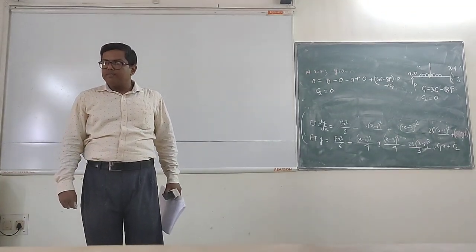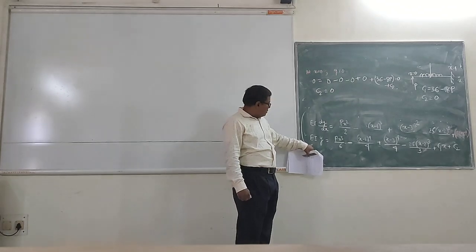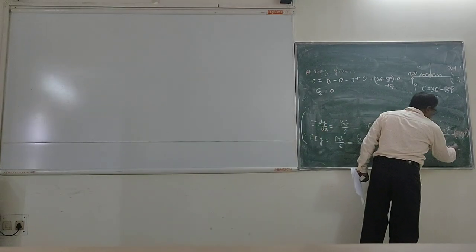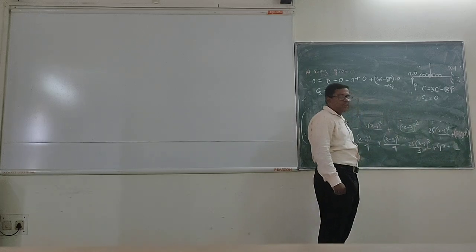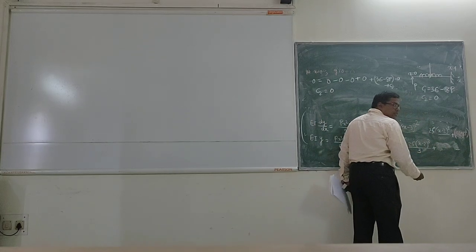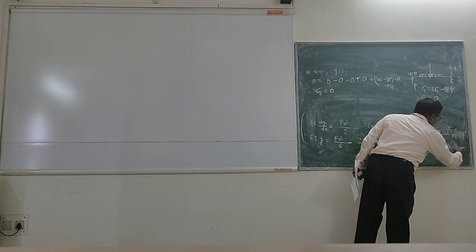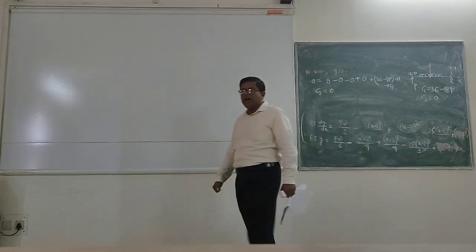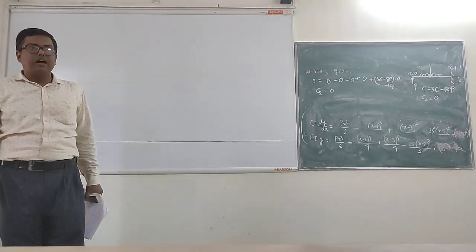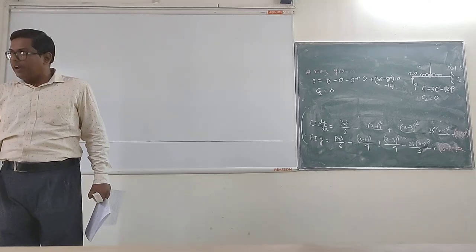Is it clear? This second equation becomes what? This C2 becomes equal to 0. So C2 vanishes from the equation. And C1x is how much? C1x is 36 minus 8p into x. So this is the final slope and deflection equations after the constants of integration you have put back into the equation, right?